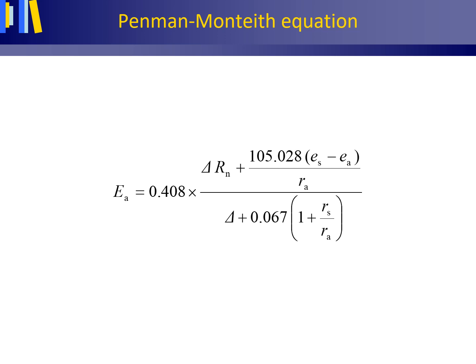Ra is the aerodynamic resistance. It is the resistance encountered by water vapor in diffusing into the air from a vegetation surface. Thus, it is the resistance against interception evaporation. It is reciprocal to the roughness of the Earth's surface and the wind speed near the surface. Both a rougher surface and more wind cause more turbulent mixing of the air and thus a smaller resistance to evaporation.